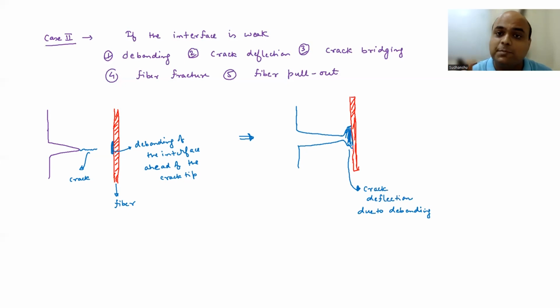And remember, in all these processes, you are going to absorb or consume some amount of energy, and thereby you are enhancing the toughness of the composite, right? Now this process will continue. So now the crack is propagating away from the fiber, right? There is a crack deflection.